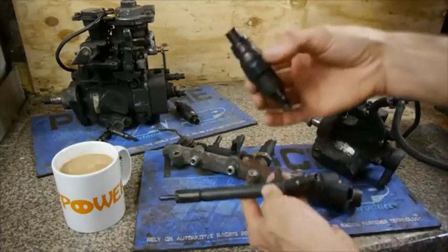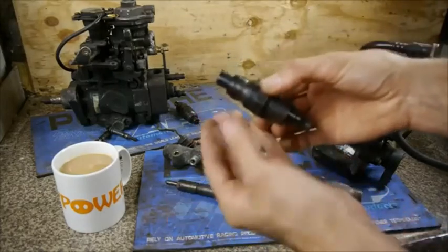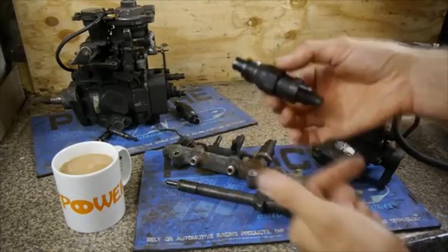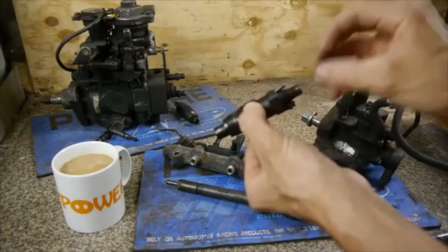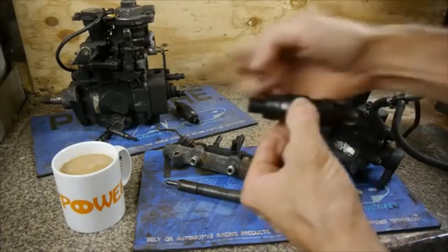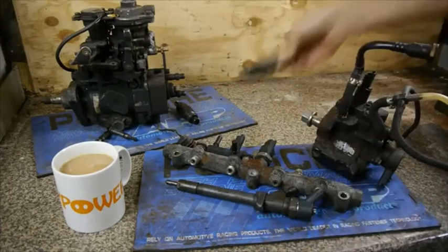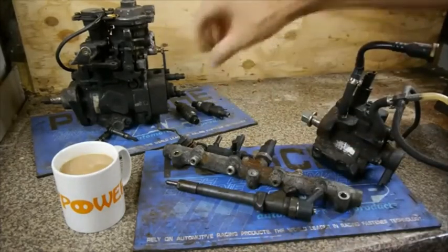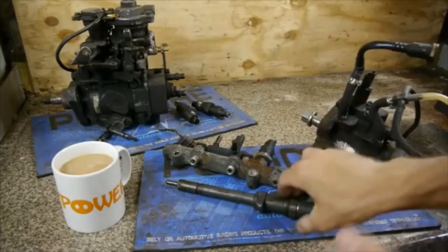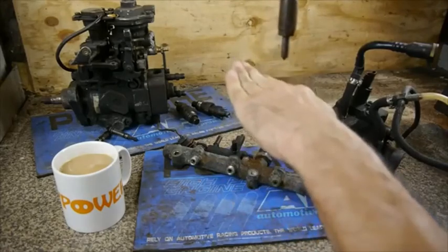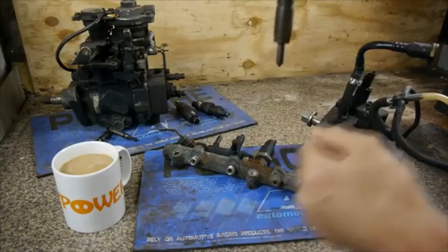Again, in size, this is actually quite a simple injector, really, and a simple system. It has a needle point injector there, and inside is a spring or 2-rate spring, and as the fuel pressure reaches a certain point when it gets to this injector, it opens, releases the seat, and the injector fires the fuel. Because these are indirect injection, the head design is also different. So these fuel injectors sit, and this little point here sits right onto the top of the cylinder, so as the cylinder comes up, it fires onto the cylinder.